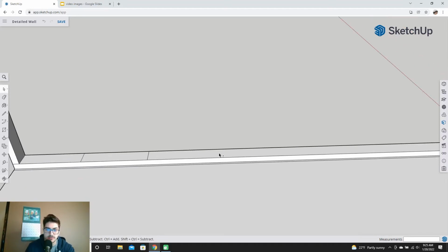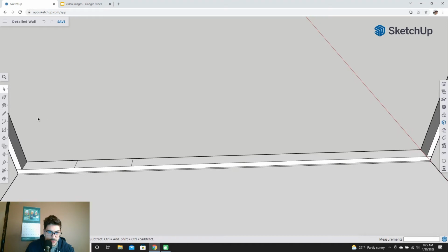So this is just kind of my cheat for doing quick measurement. I just will put down a line and I'll make it however long I need it to be. So for studs, it's 16 inches. And then I just mark it vertically. I kind of make the crossing line, and then I delete out those lines I used to mark it. So I'm going down this model and just every 16 inches putting a marker in.